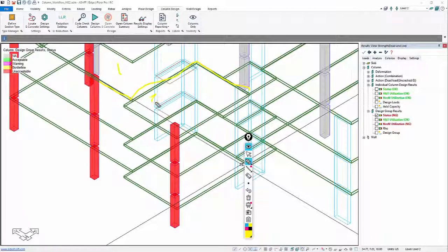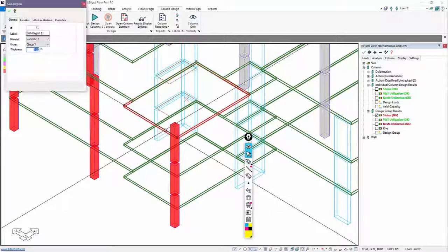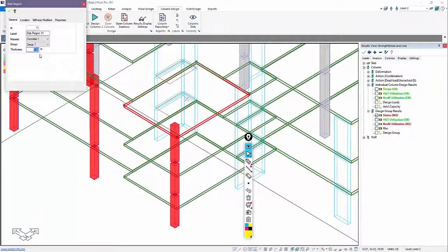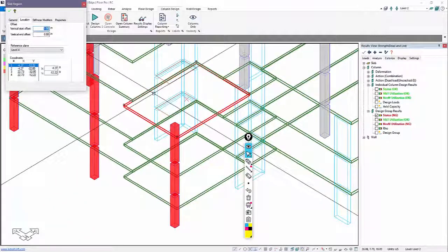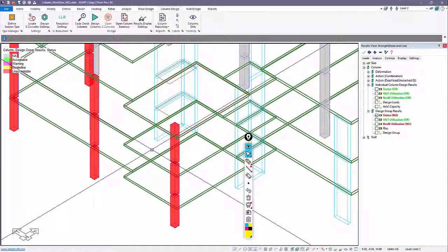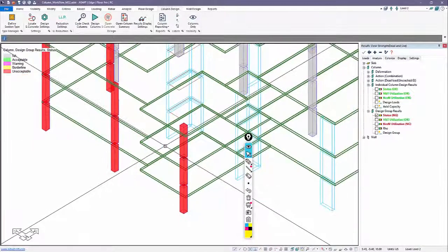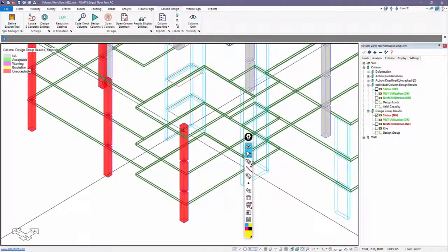So we have slab 1 and slab 2, and that repeats itself all the way down. If we look at the balcony slab, as we'll call it, this slab is actually offset by 1 inch. So we have adjacent non-nested slabs that are offset. And because of that, the program essentially triggers this issue with the unbraced length.